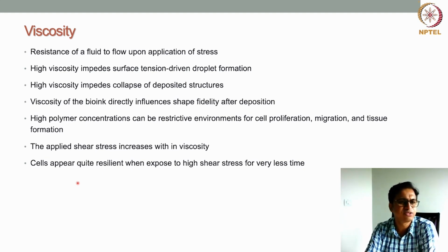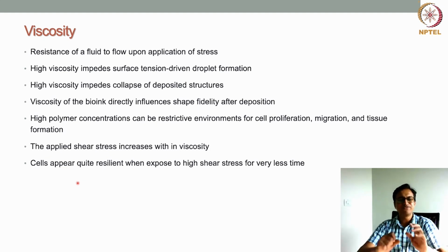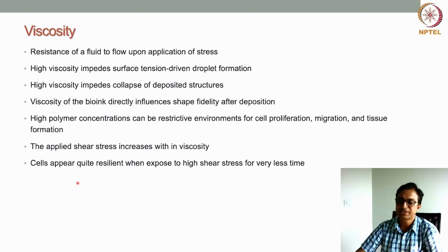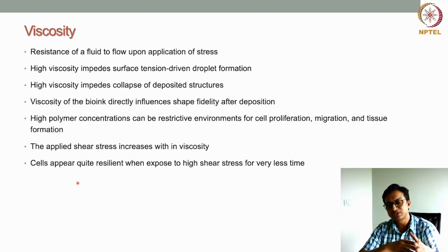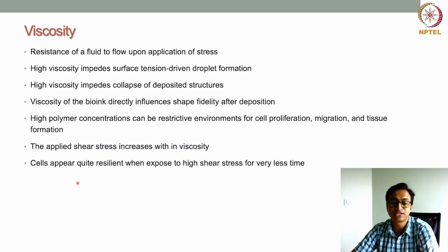Let's first start with viscosity. The viscosity, as we mentioned earlier, is the resistance of a fluid to flow upon application of applied shear stress, right? So when you apply shear stress or force on a material, the material first resists the flow, but after a certain time, it should start flowing. That resistance is the viscosity.